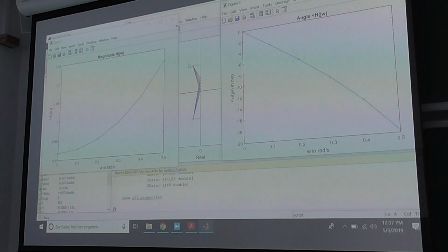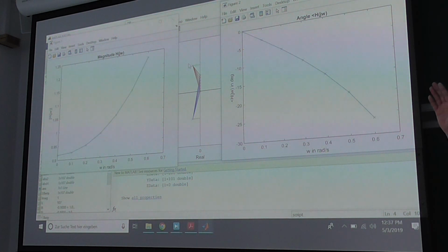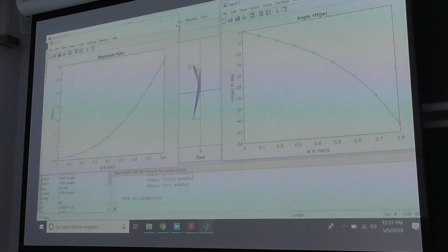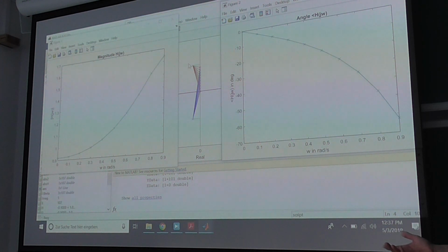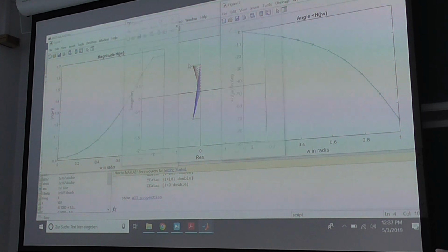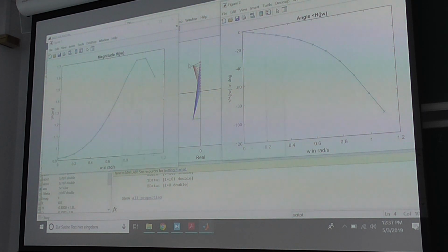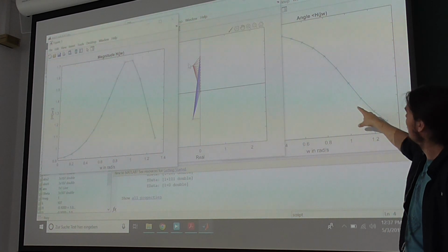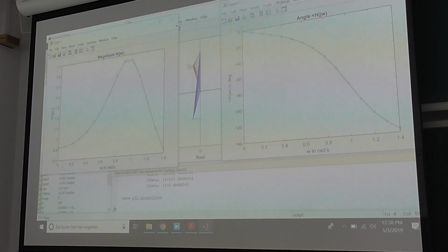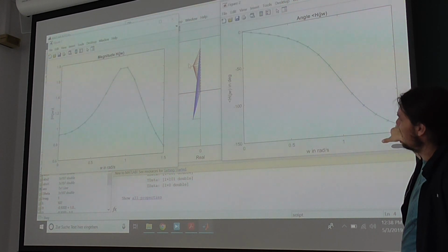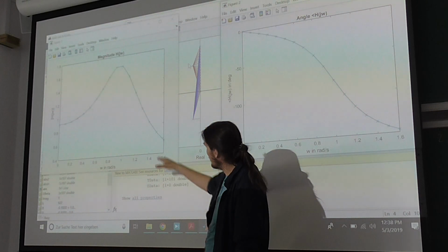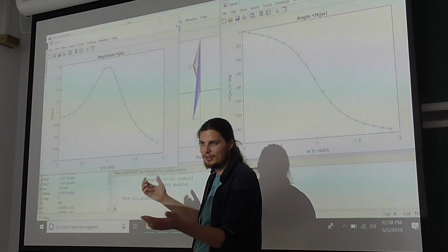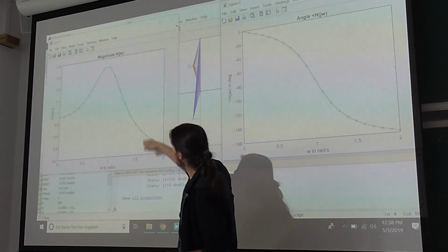And since this is not very well damped, right, the angle is really, really steep of these poles, we will see something that we should think would happen, but maybe we can also describe it together. So now we're past the natural frequency. We're well below 90 degrees, and it slowly goes where we thought, right? The angle goes slowly to minus 180, and the amplitude also drops, which makes sense, right? Both of them are getting really, really long, and 1 over really, really long is nothing. So that makes a lot of sense. It drops really quickly now.